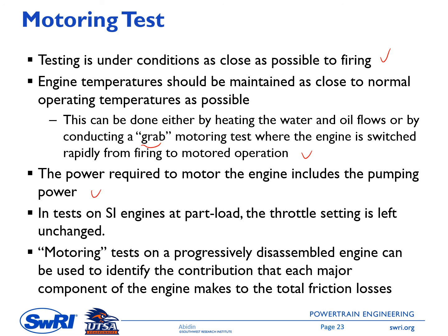In a test of an SI engine at part load, the throttle setting is left unchanged. We can also do such testing on a progressively disassembled engine so that we can identify the contribution of each major component to the total friction losses.